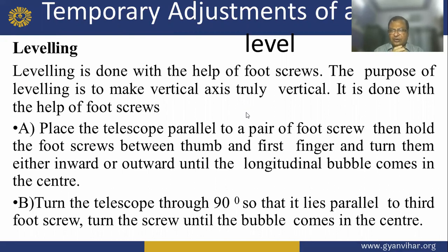Now, leveling. Leveling is done with the help of foot screws, and the purpose of leveling is to make the vertical axis truly vertical.